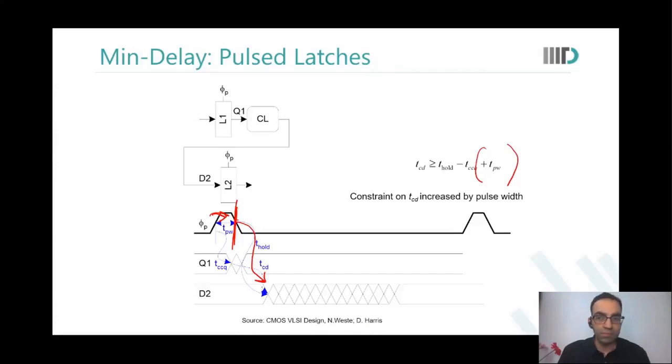Okay, right. Okay, Gagandeep? Sir, here the hold requirement is more tight and setup would be relaxed, right? Yes. So, sir, is building this type of system not more risky because you cannot recover hold once failed? Yes. They are more critical. That is why they're not very commonly used, but they are still used. As we just discussed, there is a benefit in area, there's a benefit in overall leakage, everything. So, okay, we take some risk. We'll sign off more carefully.